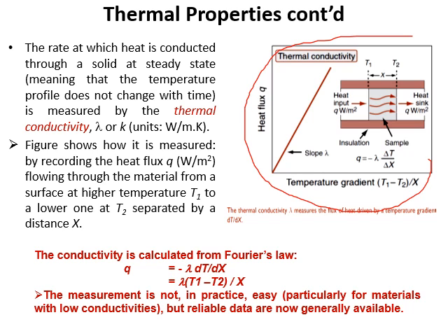So over here T1 is the higher one, this one is the lower one, and then you apply the heat over here, and then you apply a heat sink over here. The heat sink is to disperse the heat. Over here you put the heating element. Outside you have the insulator, so you put the sample right in the middle.